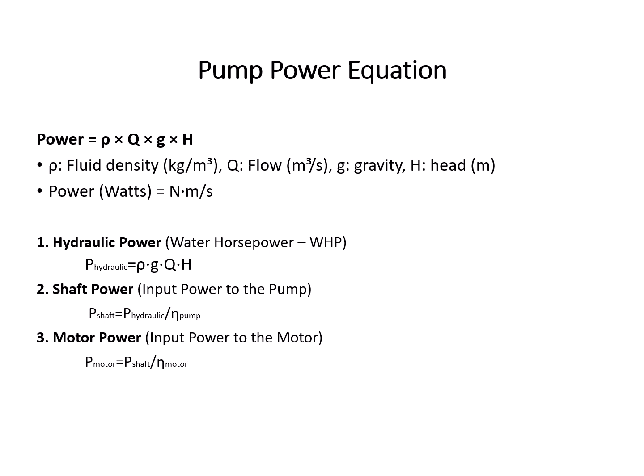This formula combines flow, head, fluid density, gravity, and efficiency if provided to calculate the required power. It is how you measure that your motor is sized right. To make sure that your motor is sized right, you have to do these calculations, and to avoid burning energy for nothing, like getting a bigger motor for nothing and losing energy.